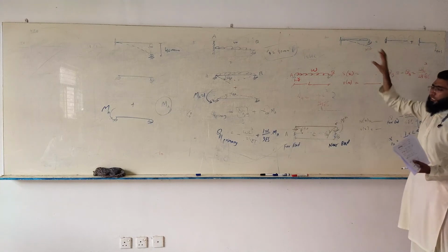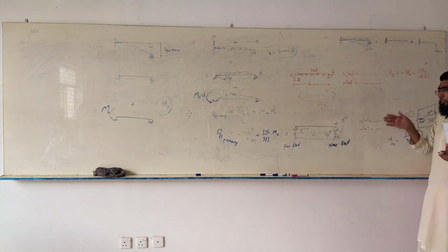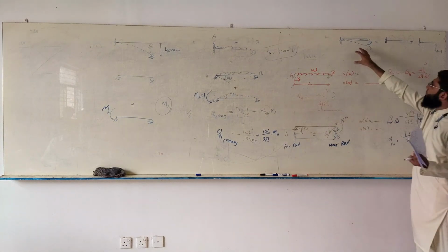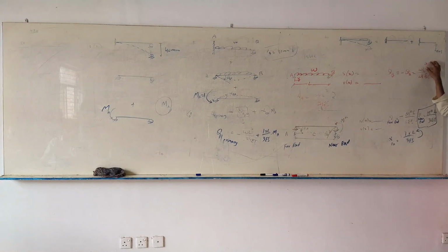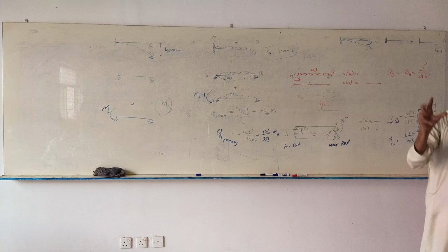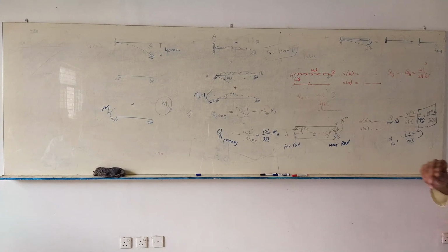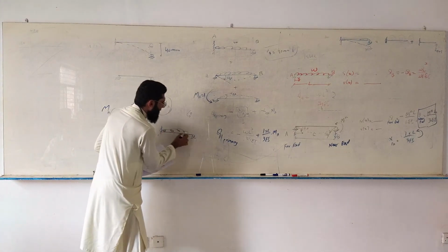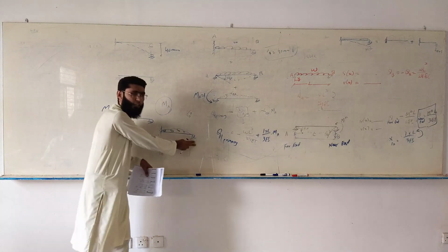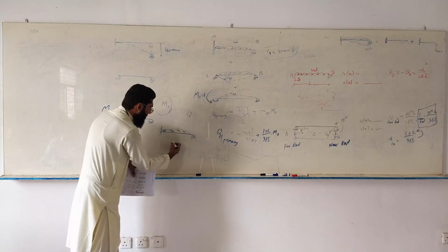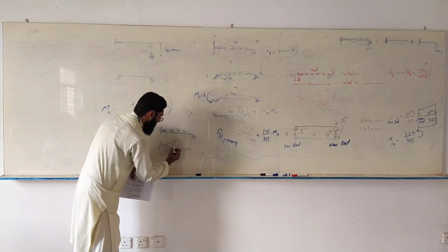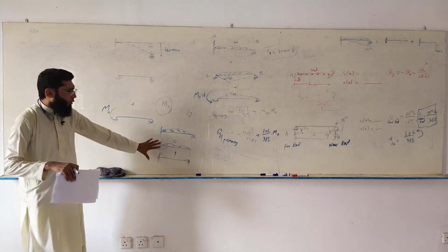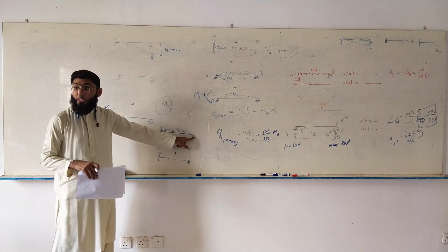So we are also using it for the purpose of calculating displacement or rotation at one point in the given beam through the principle of superposition. We are focusing on just one point, but the principle is valid for all of the points. Let me try to explain this in a different way. So this is the given beam. Let's make it simple. For the current case, I'm saying there's no settlement. There's just a loading. So when you say this is equal to this plus this, although we are using it for this point only, it is valid for all other points.